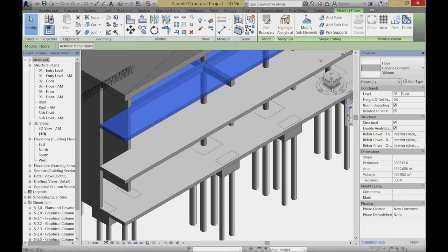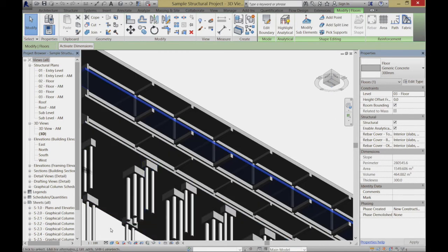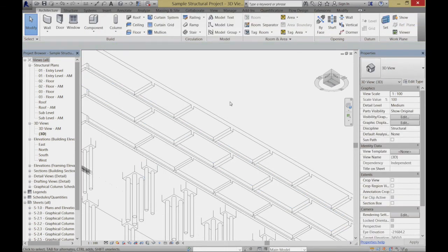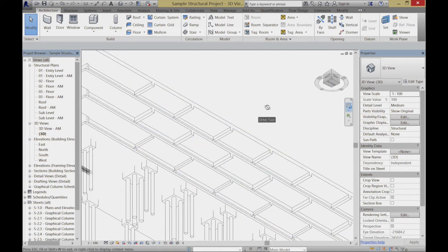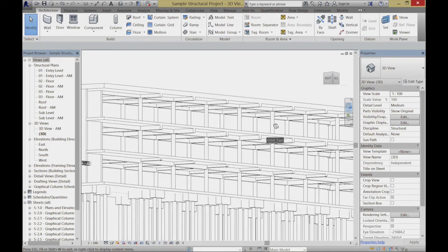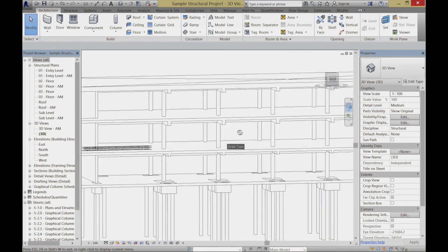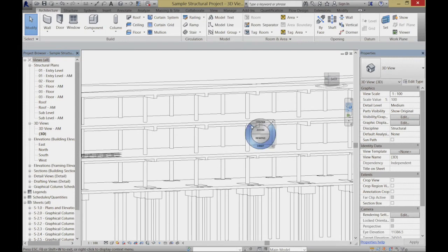If I flip it a little bit, you can start to see how the construction is working. Let me make it hidden line so it whites out a little bit. On any individual level, we have a slab, and within the slab a series of beams supporting it. But for the most part, it's just big sections of slab with beams around the edges, coming down on those round columns. That's really what we're looking at. So if you're doing your building in concrete, it may look something like this, with a very simple rectangular gridding system.